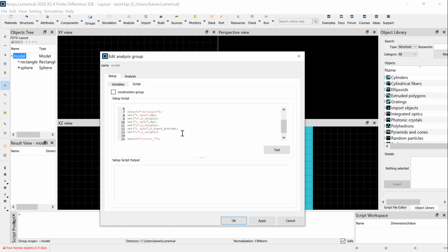So we are going to associate variables with an excitation source that has the name source 1, and we are going to use it later. For the source coordinates, we apply the same consideration as we applied to the object rectangle. Here I would like to show an example illustrating that we can introduce not only the span of the dimensions, but we can also use a coordinate minimum and maximum to define the range.